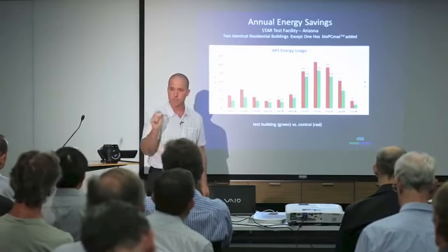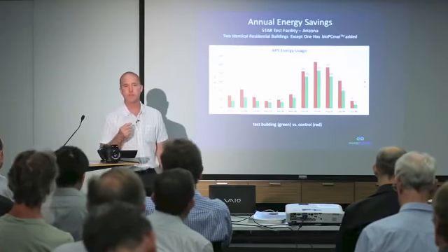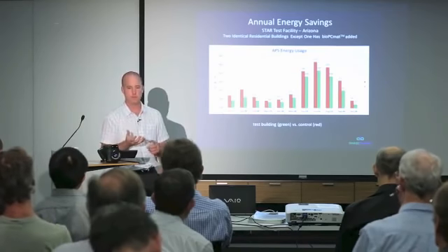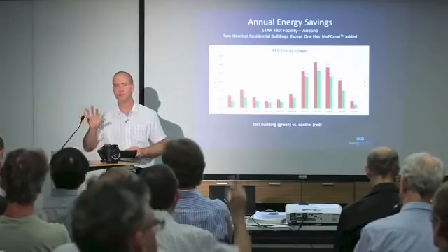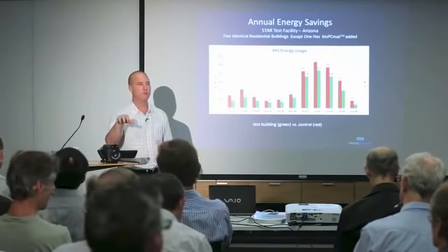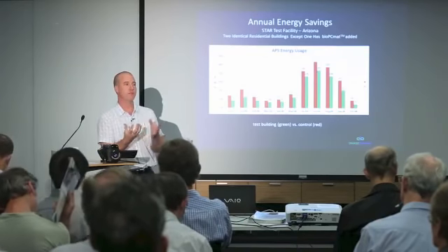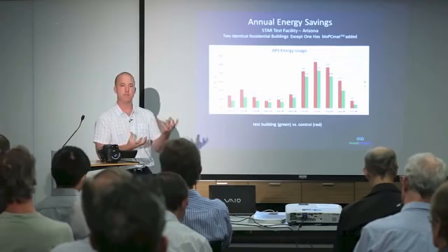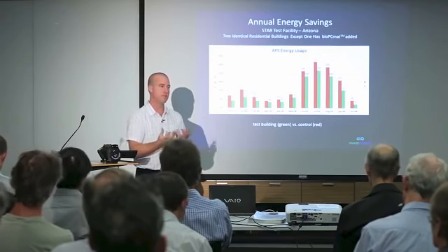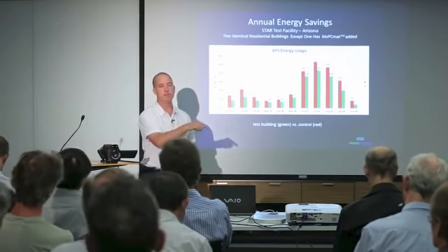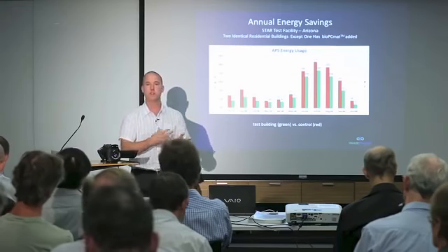So how to calculate it? You can just use the kilowatt hours. And if you have megajoules, like you might have done an export from First Rate, Accurate or BERS, you can export real data from a house that's been designed and modelled inside design modelling software. Does anybody here use thermal modelling software? A few guys? Yep. They know what we're talking about. Ask them afterwards. You can build your house inside this software, and it tells you how many megajoules of heat you're having to deal with per room on the worst day of the year and the best day of the year, etc. From that, you can calculate how many kilograms of phase change material will undo that heat or